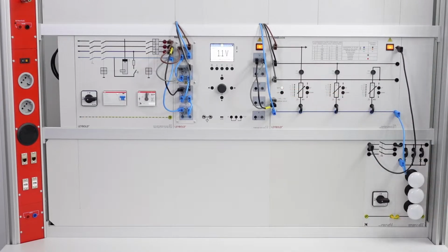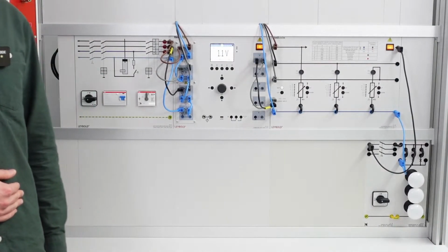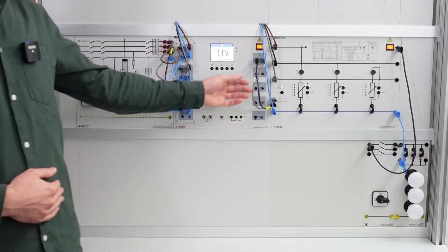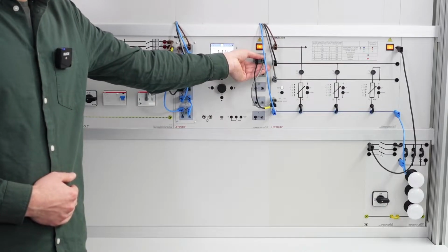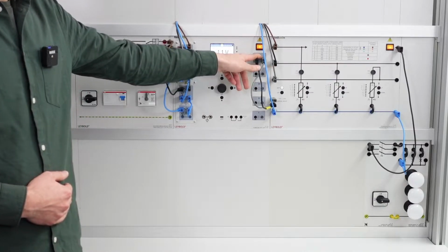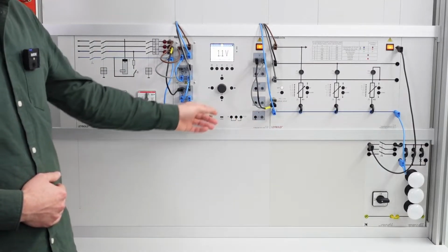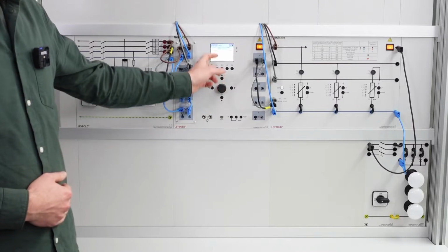Okay. The next mode is the remote control operation. For this, we use our Power Analyser CASSY Plus and use one of its outputs, output U here, and connect it to the control input. I will enable the output and select the load mode at the output.